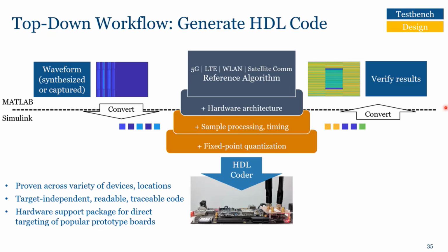We will always have the need to go back to HDL Coder. With that being said, we will always be able to use the optimizations provided with HDL Coder, like resource sharing, pipelining, running on clock rate or data rate.